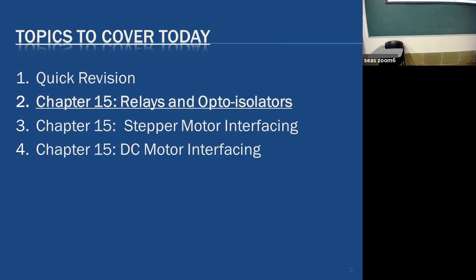So it sends the signal, logic 1 or logic 0, whatever it is. It can be pressing any key, on and off. Let us keep it simple. You need some translation, so you are controlling 230 volt AC using a DC device. There should be some receiver, and ultimately it turns the 230 volt on or off. So there are many cases where we need these relays and opto isolators, and we study a few of them.